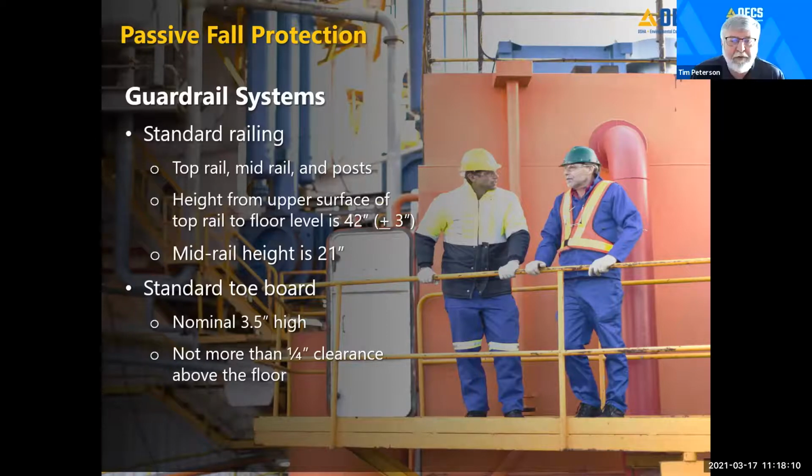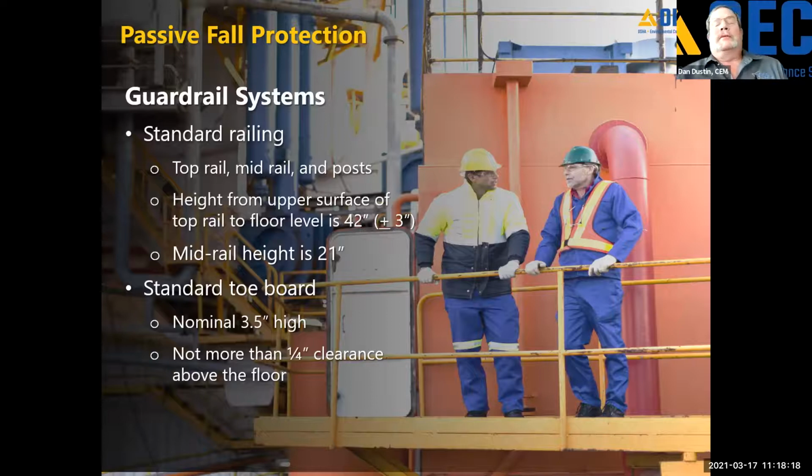You stated that the toe board, if required, so there are options out there where the toe board is not needed. There would be spaces where there is not a requirement to have a toe board. For example, when I put a guardrail system up to protect scaffolding, I don't necessarily have to have a toe board to prevent dropped objects as long as the area below the scaffolding is protected and nobody can get in below it. So when I'm performing work at height, if I can protect the people that could inadvertently walk in below by barricading the area, you kind of obviate the need for that. But our recommendation is you always put a toe board up if the potential is there to drop stuff.